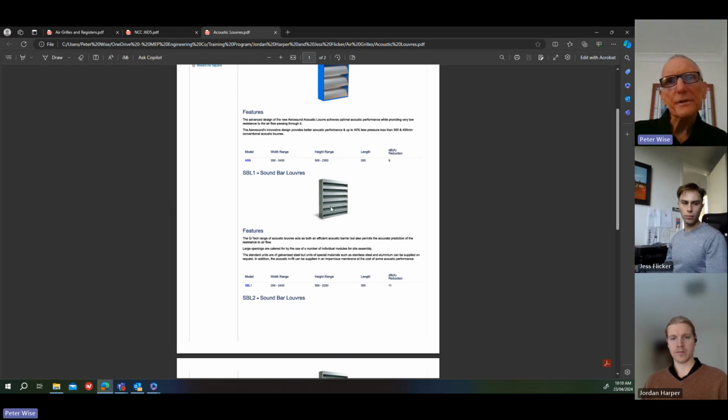These sections, the modules in there, are actually internally insulated perforated panels with a metal face. So it's like an attenuator, but they're not as long as an attenuator. And these panels slope upwards so that the moisture is not coming in. You've got to size them correctly. And if it does get on the face, it'll drain back out again.